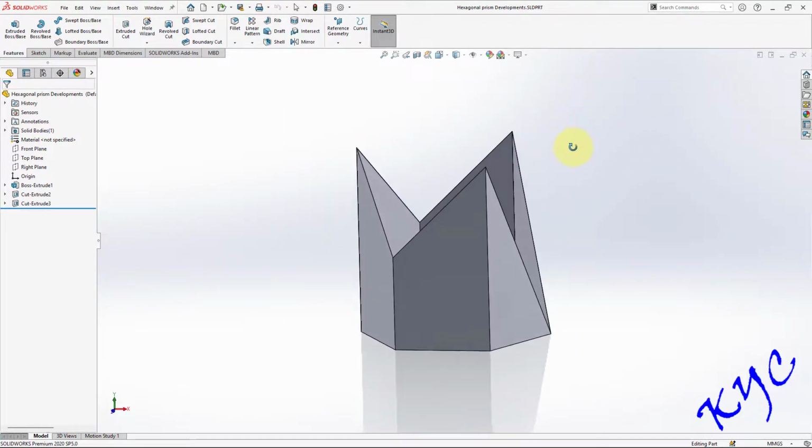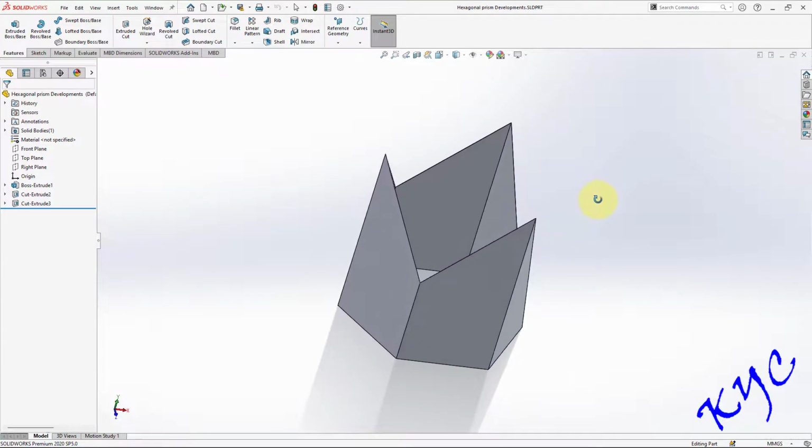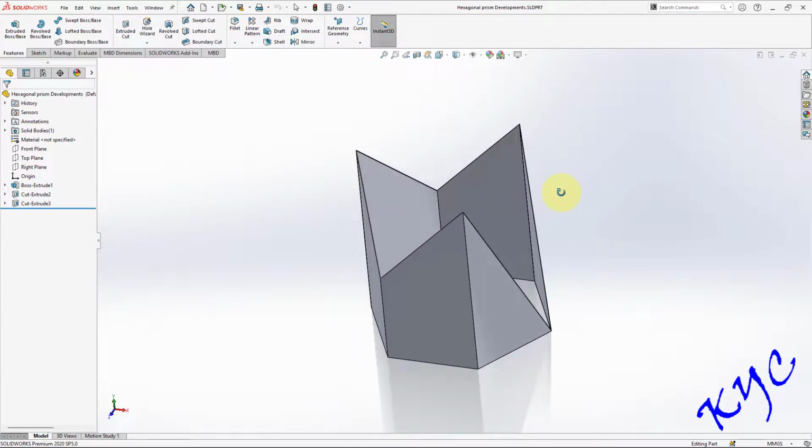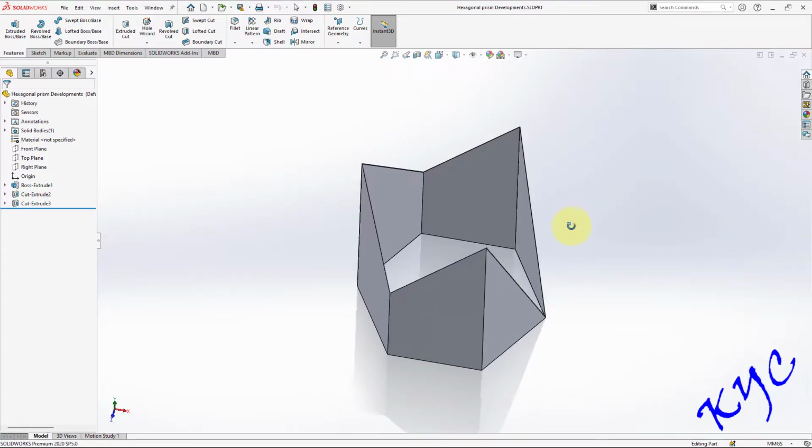Now let us try to find out the section points. What do you mean section points? The intersection of the section plane with the edges of the solid. Now if you carefully observe here, the section plane is intersecting here, here, here. So totally, if you observe carefully, 1, 2, 3, 4, 5, 6. So there are 6 section points. These points have to be presented on the development, and if you connect those points, you'll get the development after sectioning. So this is the theory behind development. Let us start.